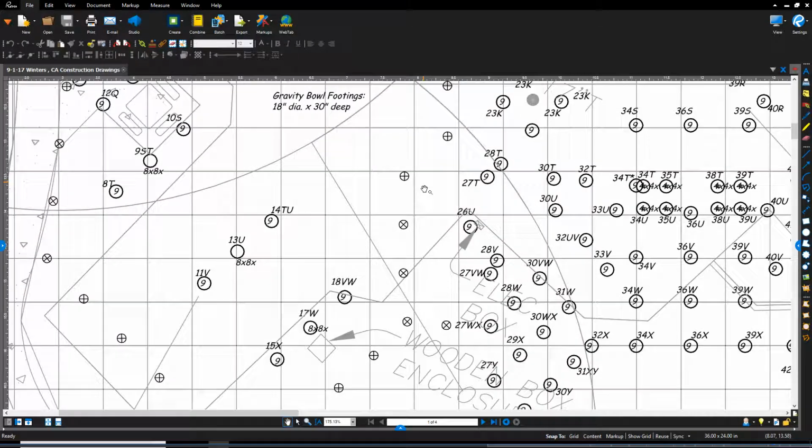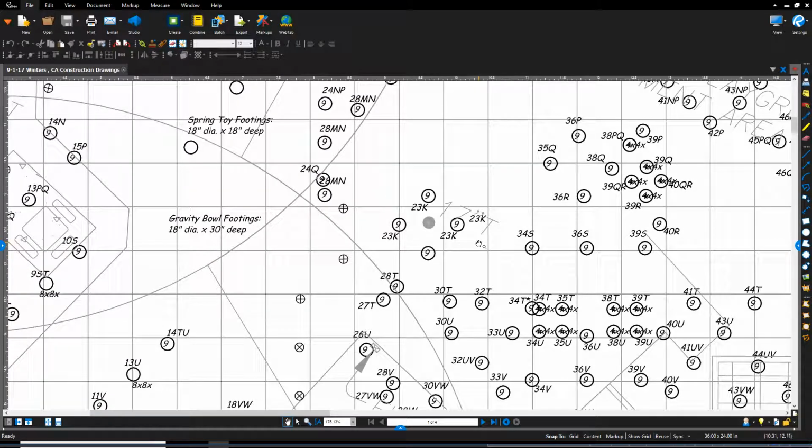And that gives you everything. If you want to turn all the points on to kind of get an overall view, you can keep the grid active, you can do what you want, but then you can take a step back and verify what you're doing, that you've got all these holes, and you can kind of as-built them as you go along. So you're going to shoot a point where you drilled, and that way you're going to make sure you didn't miss anything.